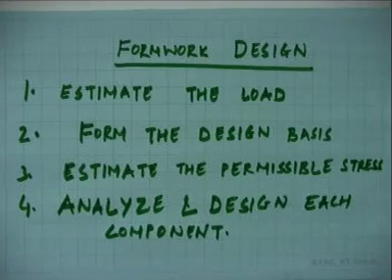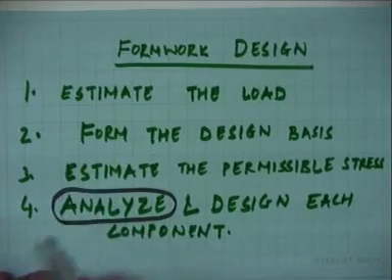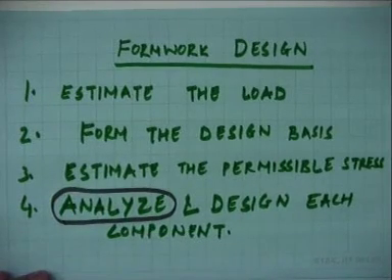First is to estimate the load, then form the design basis, estimate the permissible stresses depending on what material you have chosen, and then analyze and design each component. When you say analyze, depending on the importance of the structure, the analysis could be rigorous or it could be approximate.